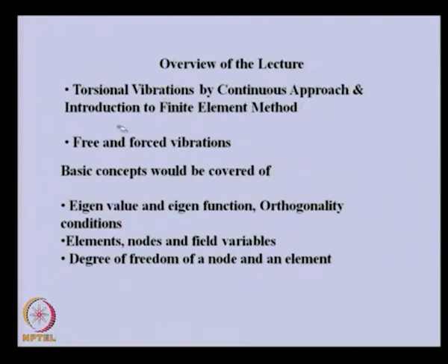In this, free and forced vibration is the main analysis which we do, and some concepts like eigenvalue, which is nothing but natural frequency, and eigenfunction. In a discrete system it was nothing but the mode shape.